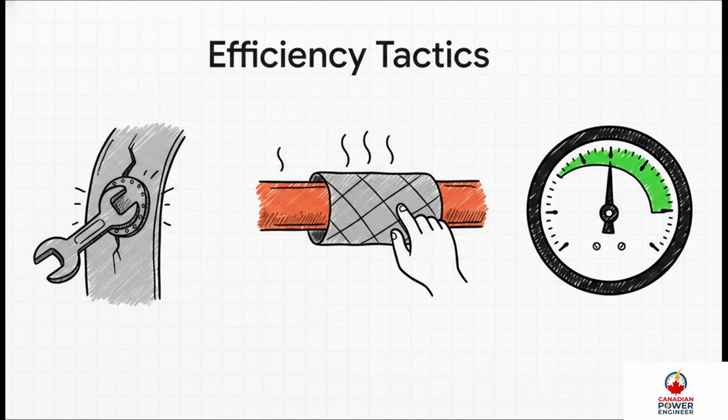Finding and fixing boiler casing leaks prevents excess oxygen from fueling NOx creation. Maintaining your insulation prevents thermal losses that would force you to burn even more fuel. And running your equipment as close to its maximum rated load as possible ensures you're operating right in that peak efficiency window it was designed for. Remember, every single drop of lost efficiency translates directly into excess emissions.